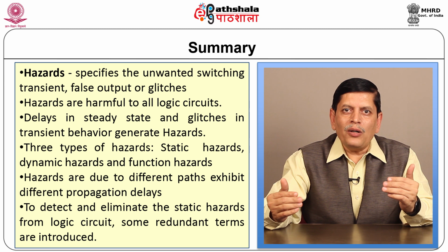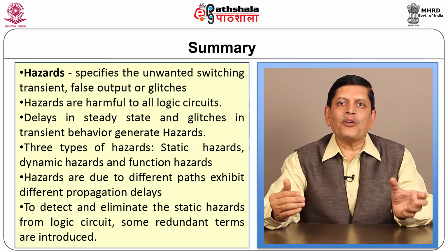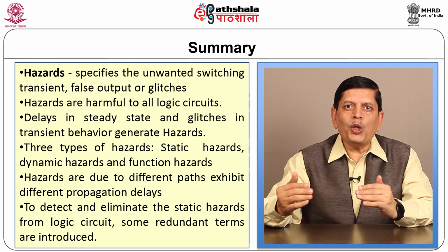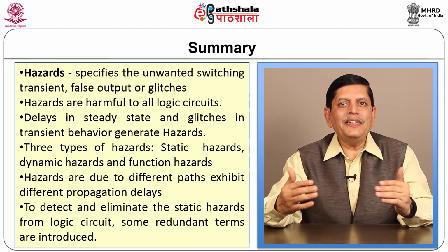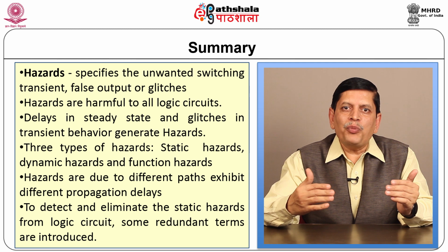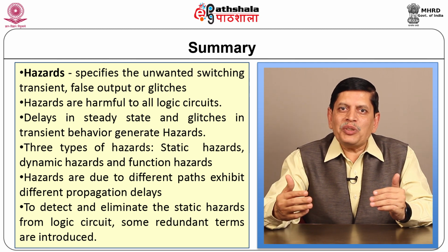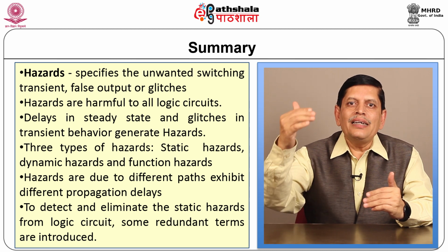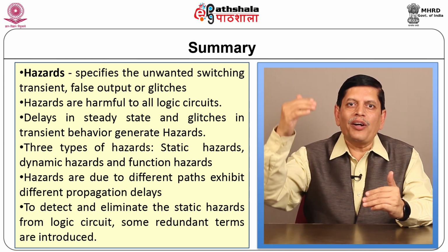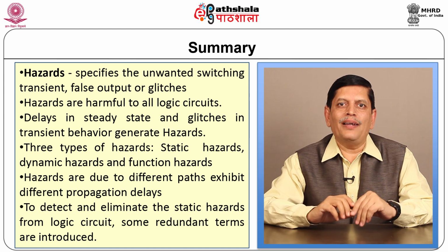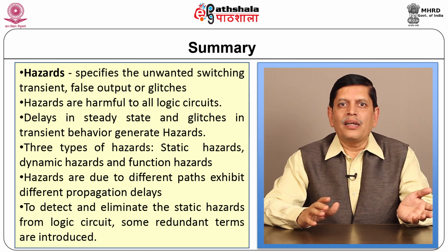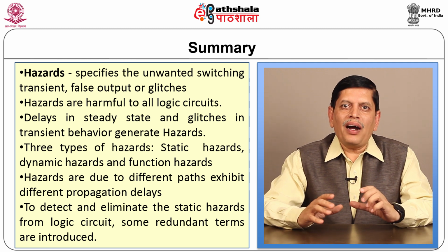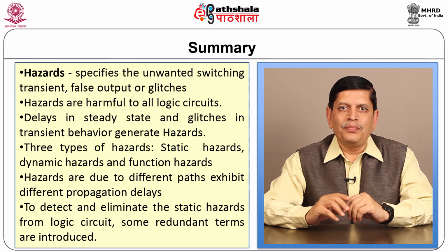In addition to that, there are dynamic hazards, wherein the input to output transitions will have a certain number of changes at the output. If the output changes more than once, say we have listed that if the input changes 3 times, then naturally the output will go momentarily 3 times to the unwanted state and come back to the normal value. In static or dynamic hazard, there is an important part, that is the propagation delay.